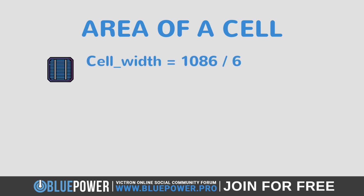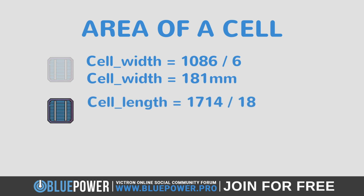Next, we need to find the width and length of an individual cell. To do this, we take the inner width of 1,086 millimeters and divide it by the number of cells, which is 6. This works out to 181 millimeters. We then do the same with our calculated length of 1,714 millimeters, except we are dividing it by 18 cells. This works out to 95.2 millimeters.